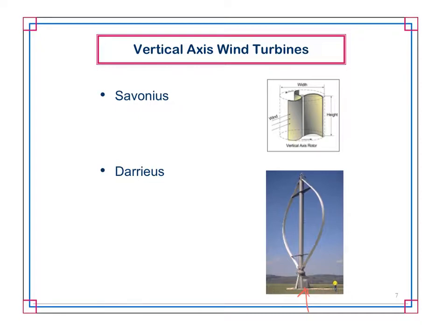It's very difficult to see unless you're looking at the slides, but you actually have guy wires, right? And so the foundation design can be a lot more simple because if it's a horizontal axis turbine, it has to be able to account for all the forces that are trying to essentially tip the tower over. Where in this case, all you have to do is guy it out, and because of the mechanical advantage you have with the guy wires, it's a much more basic and simple foundation design.